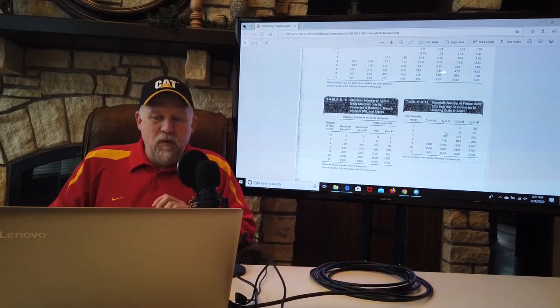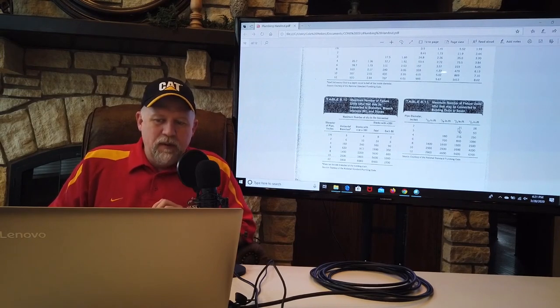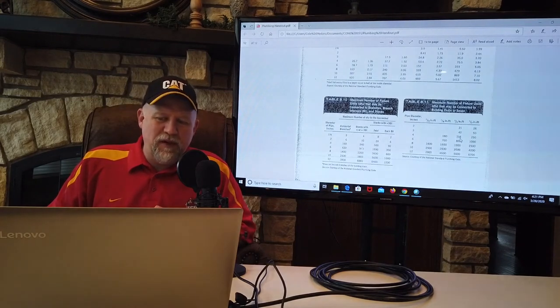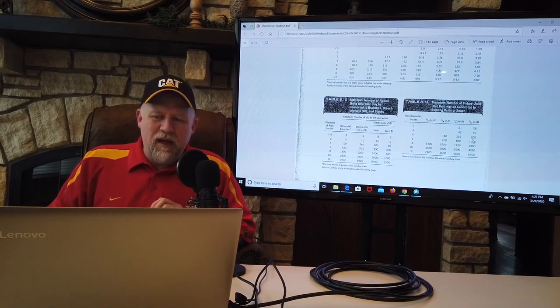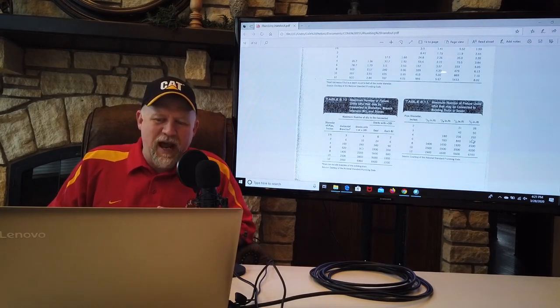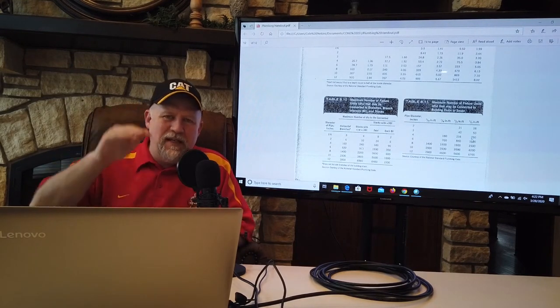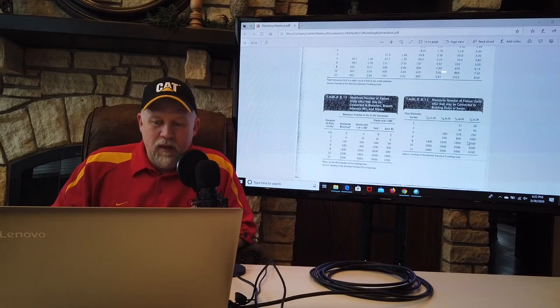Now, if you increase the slope of that pipe, that 4-inch sewer main can handle 216 drainage fixture units if it's sloped at 1/4 of an inch per foot, and then up to 250 drainage fixture units at 1/2 of an inch per foot. 1/2 of an inch per foot of sewer pipe slope will get you very deep in a hurry, right?